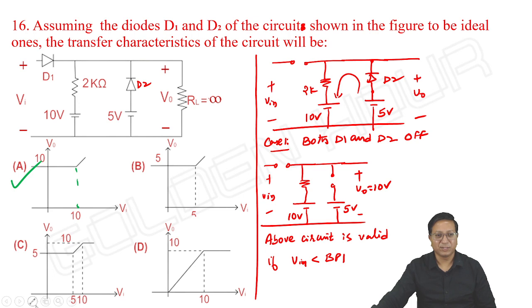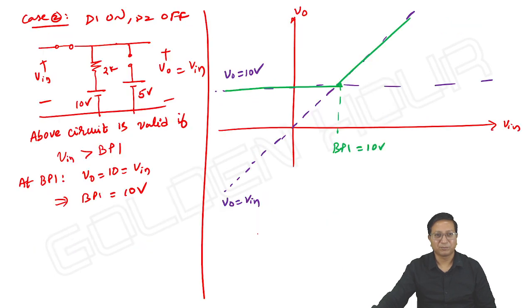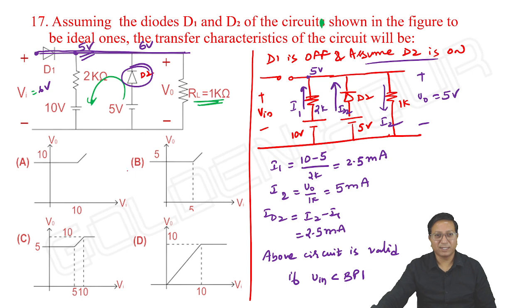And coming to the second problem, here by connecting a load resistor of 1 kilo ohm, initially D2 is on. Okay, we have seen. Later, once the input goes above the breakpoint, once D1 is on, automatically D2 will be off. Okay, and there is no point of observing this 10 volts as a breakpoint or output maximum. So very, very interesting problem it is.